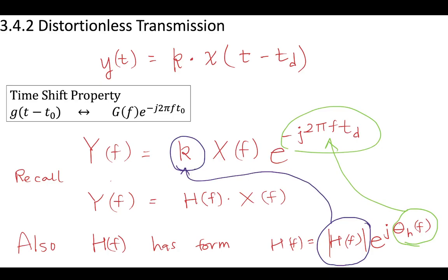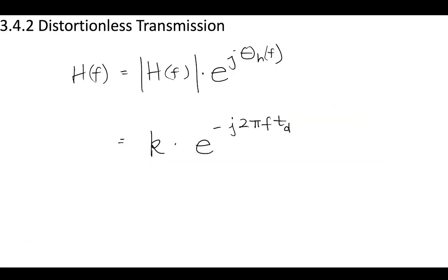So the multiplicative constant K would be the amplitude response of the transfer function. So this is the amplitude response of our communication channel. So as our signal passes through all those digital analog converters, the channels, etc., what does the amplitude response look like? And then as the signal is sent at some time, and there's some delay as it passes through the channel, that delay is going to appear in this phase response.